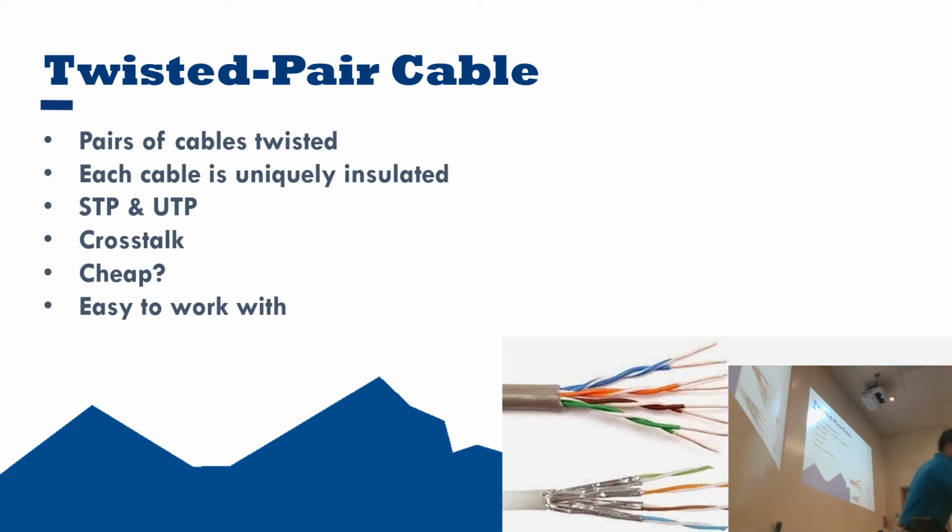Since this is just a junk cable, I'll just go ahead and show you. If you bend it like this and you put a kink in it, you're liable to damage the inside strands. And if the strands are damaged, obviously they can't pass a signal. So it's not good to do this. Don't do this on any real cable, especially not one in production. But that one's just a piece of junk we can just play with however we see fit.